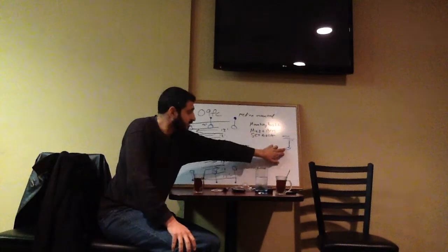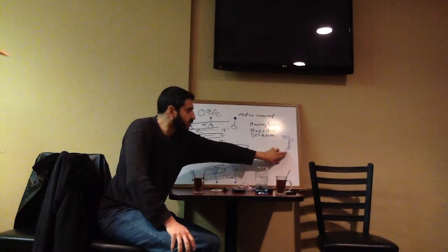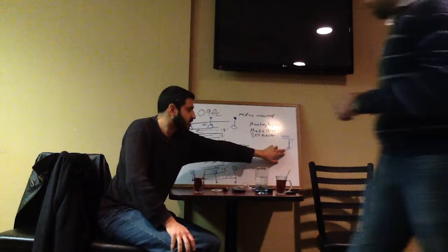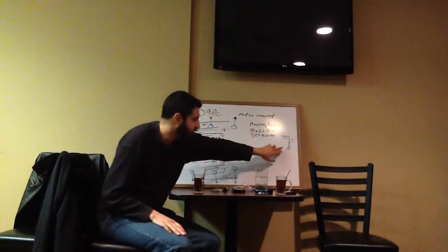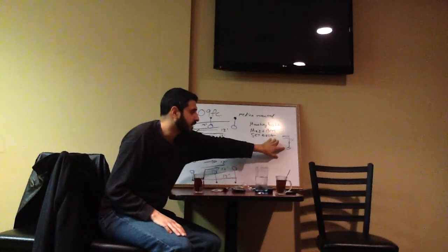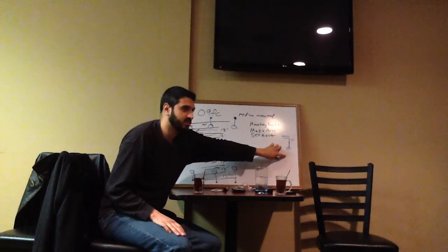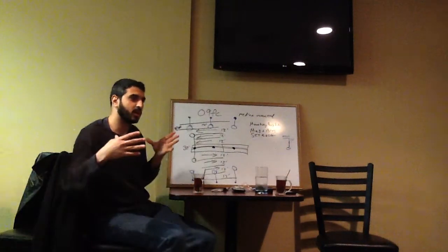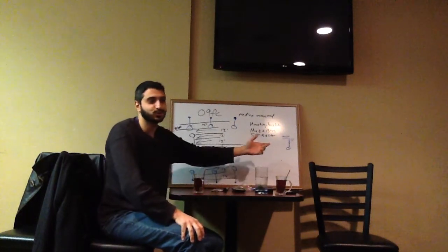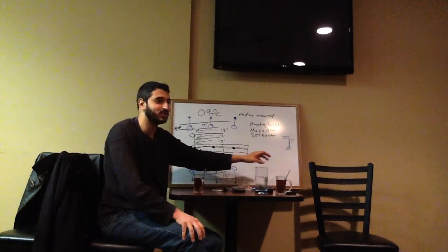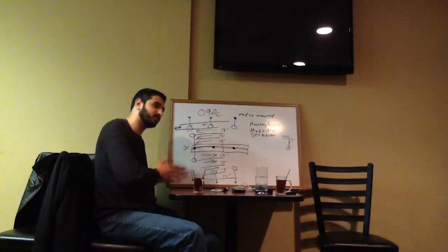And just a quick note about the foundation, it's more of a structural design. But that foundation is gonna extend further down into the ground. It's not just a pad. A pad will be kind of 6 inches or something like that. For a 50-foot pole, we use a 7 to 8 foot deep foundation that's 2 feet wide, 2 foot diameter. So it's a structural design. I wouldn't know exactly how it is. We have standard foundations that we use for 50-foot poles.